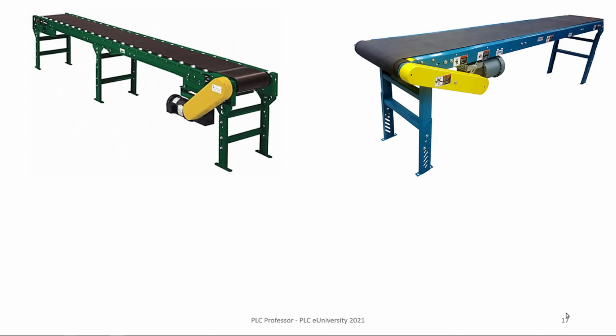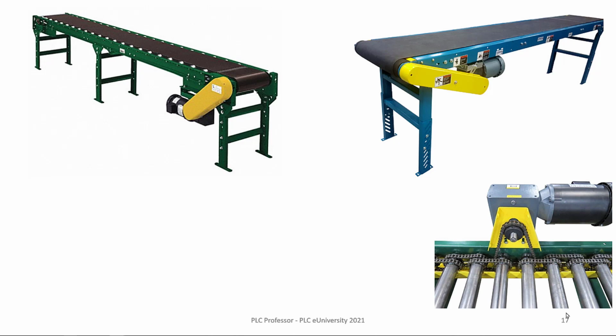This is a roller belt conveyor, meaning that the belt travels on rollers with bushings or bearings. So there's a lot less friction involved, but it can be kind of bumpy if you have heavy, small objects because they tend to want to deflect the belt a little between the rollers. But both these conveyors do the exact same thing. They convey something from one end to the other. Now this is a live roller, no belt.